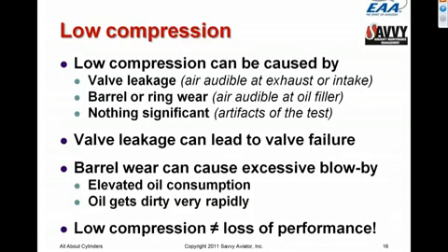Another way that we can verify leakage past the rings is by watching oil consumption and watching the color of the oil and seeing how quickly it gets dark after an oil change. If we're having leakage past the rings in actual engine operation, oil consumption will be elevated because the crankcase will be pressurized and it will be blowing a lot of oil mist out the engine breather. And because of the blow-by, a lot of combustion byproducts will be getting into the crankcase, and we'll see that in terms of the oil starting to get very dark and opaque quite early after an oil change. So we want to keep track of all of those things.